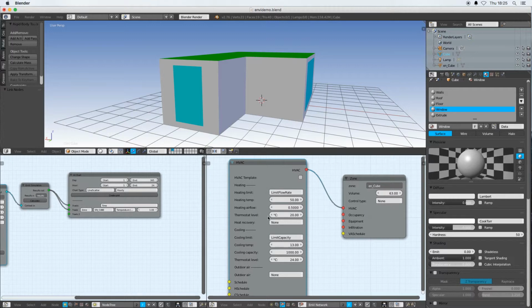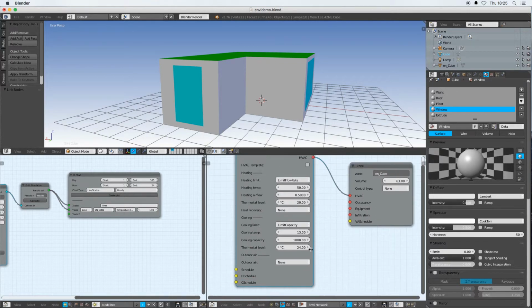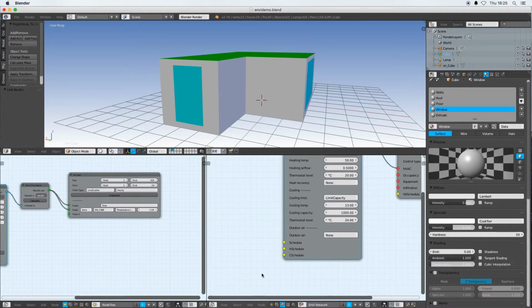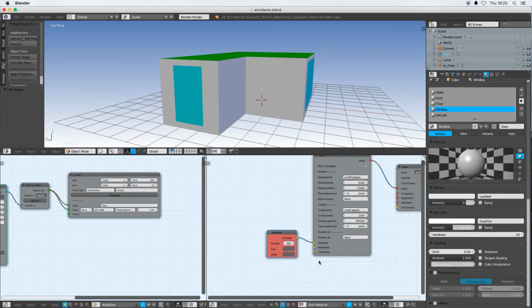The sort of details of the options within this node and the scheduling of when the system is on and off, and the heating and cooling temperature set points, that's kind of covered in the EnergyPlus input-output manual. I will just show you how to add a schedule. It's in the Schedule Nodes menu. So I might say this is a schedule that's going to apply to when the heating and cooling system is in operation and not in operation.